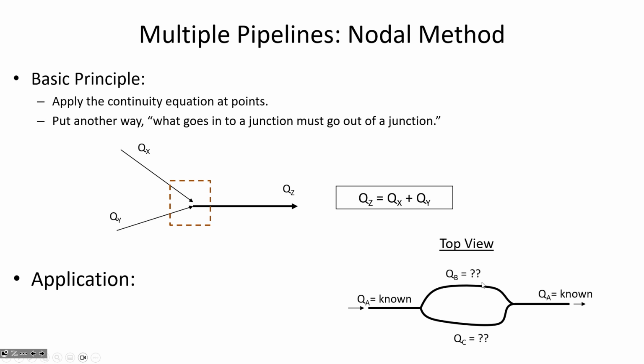We have to know the flow rate, because all of the models we use to determine the pressure downstream depend on some understanding of what's the flow rate through the pipes, whether it's the Darcy-Weisbach equation or the Hazen-Williams equation, both of those, to know how much energy loss there is through the pipe. You have to know either the flow rate or the velocity, and actually, if you know one, you know the other, because they differ just as a function of the cross-sectional area.